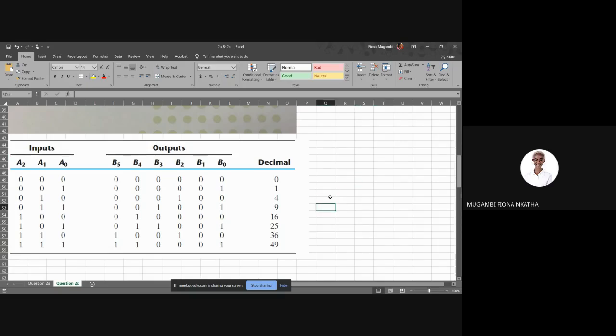We'll just get rid of B0 and B1 in our truth table, or in other words, the output lines for our ROM will reduce from 6 to 4, because we can just set B1 to 0, and set the line connecting B0 to be equal to A0.